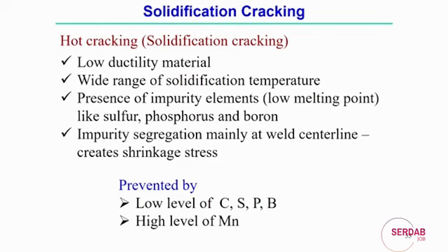Also the impurity segregation that occurs at the weld center line sometimes creates solidification shrinkage stress, and that shrinkage stress induces the hot cracking phenomena in the welding process.